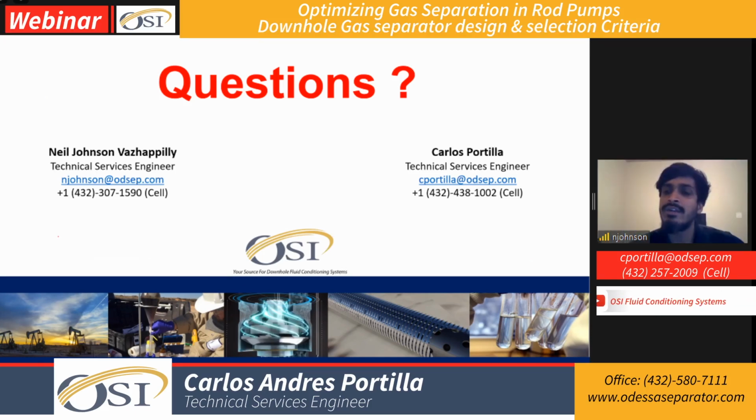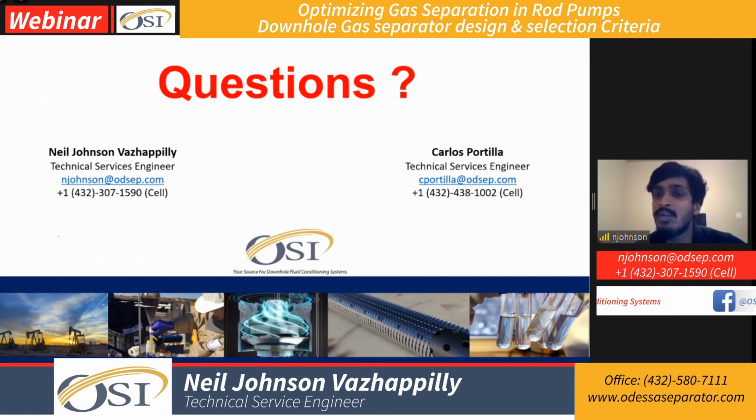One of the things I did mention when it comes to selection criteria, and we have a question on the GLR limitations of just a modified Mother Hubbard style, is that we can improve that separation efficiency. Like I mentioned, it does not have to be just below 1500 GLR. We can extend that a little bit more, by adding special components like the screen, which helps the overall separation efficiency, and multiple gas bodies, which not only increase the storage sump inside the tool, but also, from the outside, agitate the gas enough to separate as much as we can, and obviously the gas vent that we just mentioned.